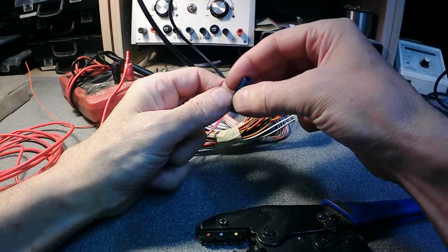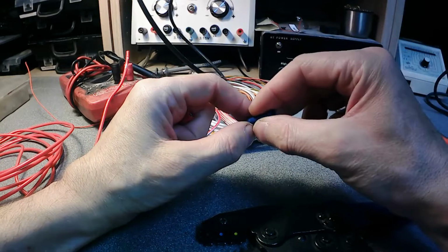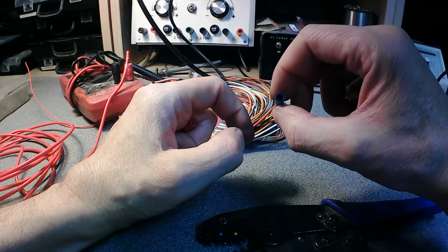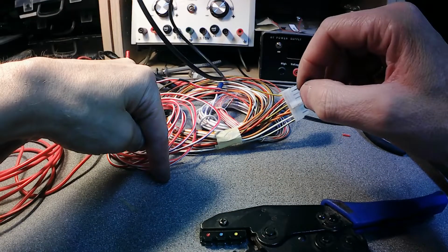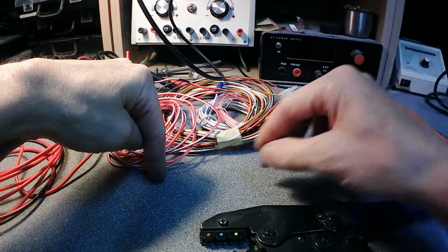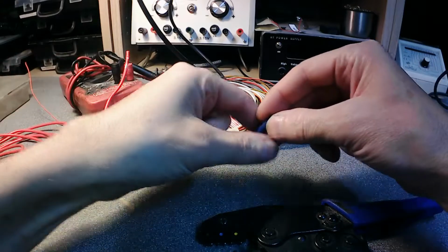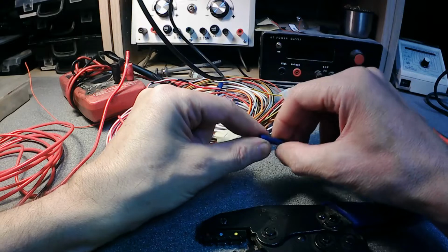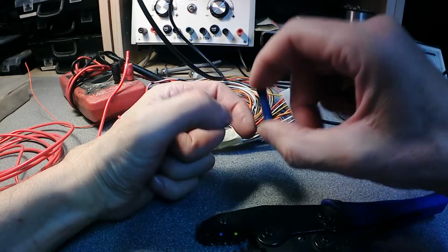But anyway, these connectors for sure will be necessary. There is also a straight connector just to connect wires, not recommended. A wire should start from the point of power and finish at the appliance as one wire. Every connection which we hide behind a cabinet is a weak point of the system.